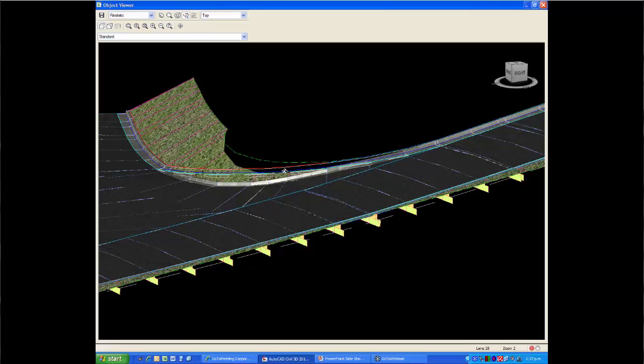Actually, it's around the other way. Looks like the model's updated already. Okay, the straight line is the lines that are up above here. The profiles that are up above there are the straight lines. So you end up with a kink down on the left-hand end here, where the intersection hits the side road. You'd end up with a kink in the curve return at that point. What we've done is smooth that out by putting in the vertical geometry into that curve return, and we get a nice, more smooth flowing effect around the corner. You won't see that when you're driving or walking along there.